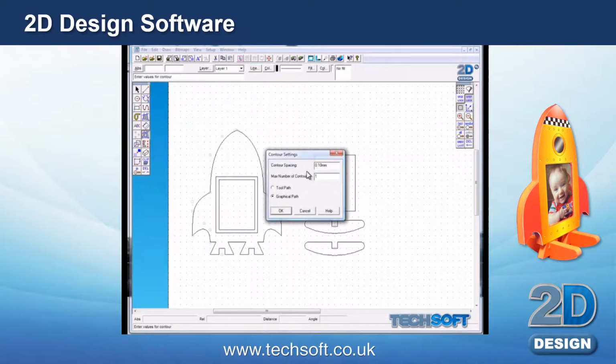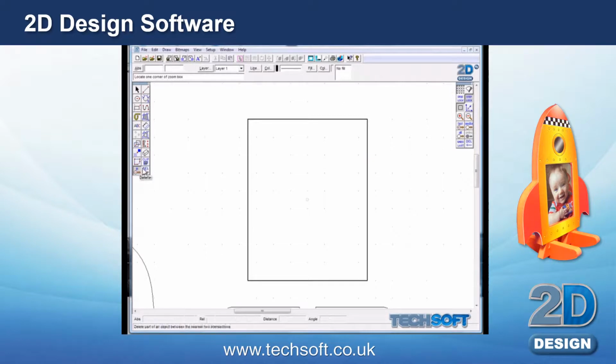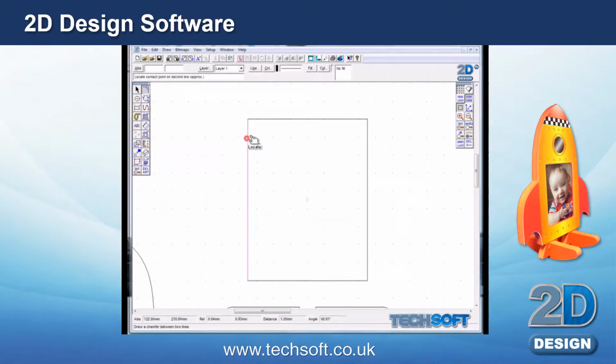Now I'm going to make this rectangle a little bit bigger by 0.1 mil. OK this, select the outside of the rectangle. I'm going to zoom in so we can see what we're doing. We're going to delete any, so we can do the whole rectangle at the same time. Now this is 0.1 mil bigger all round. Go to the chamfer tool, we're just going to take the corners off so that it'll fit in. And just select each line on the corner.